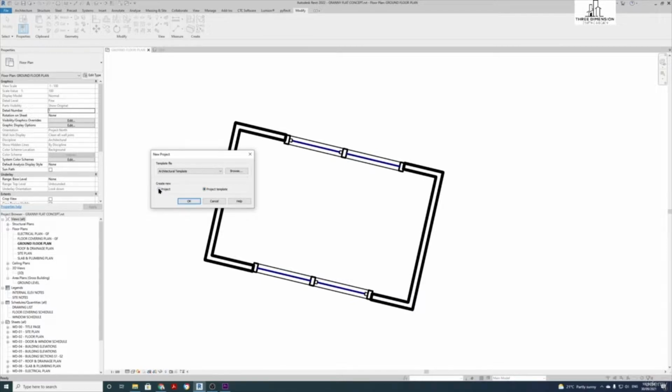Personally, I recommend just using the Create New Project tool even to make templates, because that way, if you use the project to make a template, when you're in your Windows Explorer, you can just double click on your template file. That'll open it up as a project, and then you can work on it and save it, and it'll save as a project. Because if you open a template file through your Explorer browser, when you go to save it, you can only save it as a template.